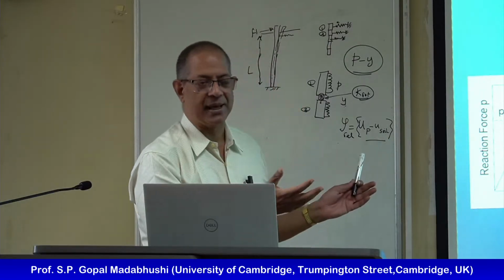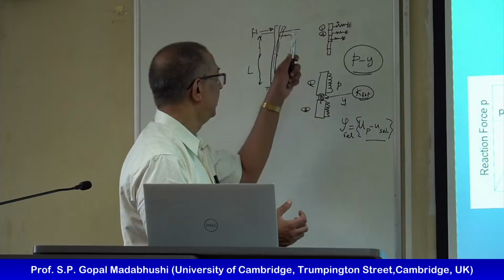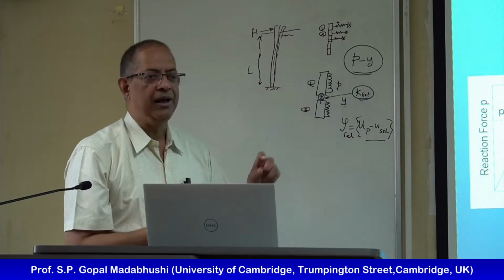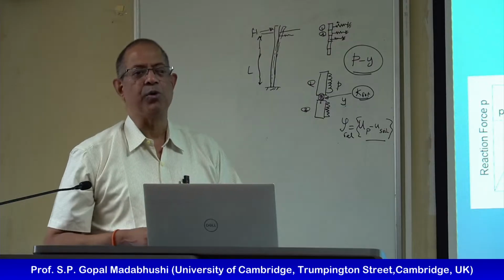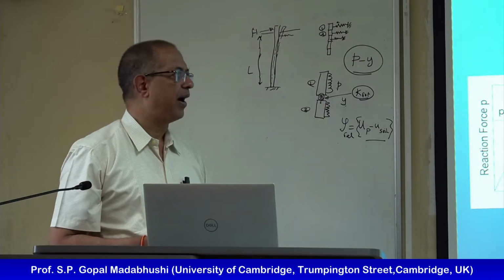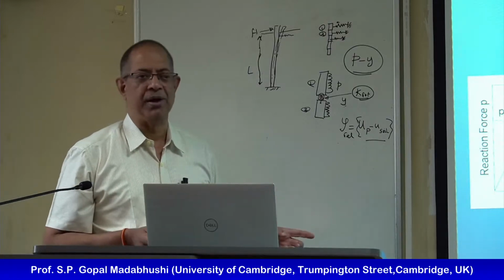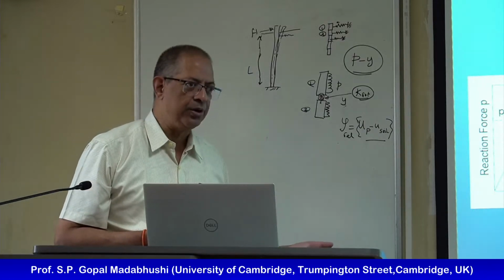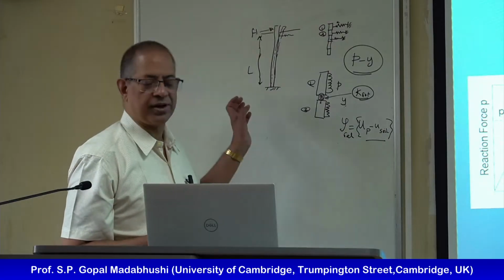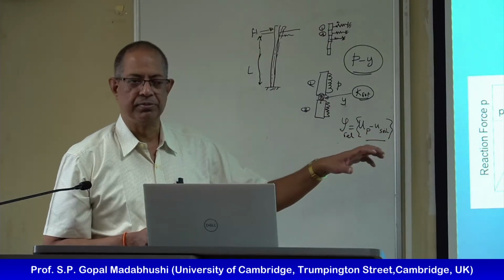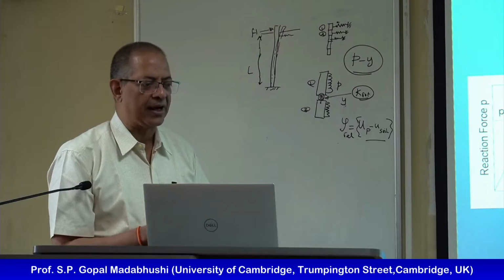But it's exactly the same concept as this. This was originally developed for lateral load on piles, but what we are now saying is our load action is not coming because of some external load, but it's coming because of the soil trying to move down slope, in the context of lateral spreading.